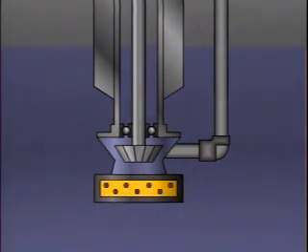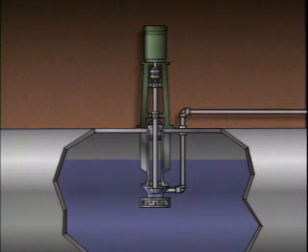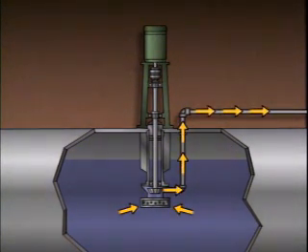The suction is covered by a strainer, which prevents trash or debris from clogging the pump and causing excessive wear. The pump's impeller is also submerged in the liquid. This helps to ensure that the pump is always primed. This means that the casing is filled with the process liquid. During operation, liquid is drawn in through the suction and then pumped through the discharge piping, which extends up and